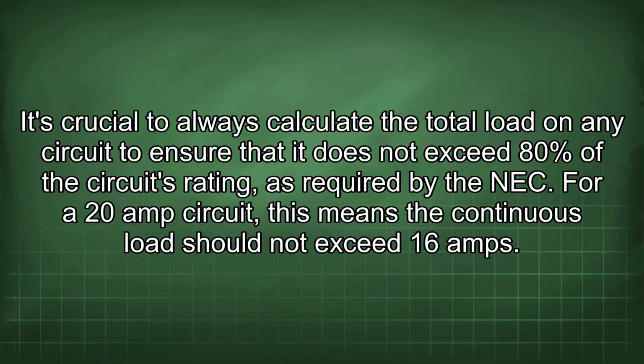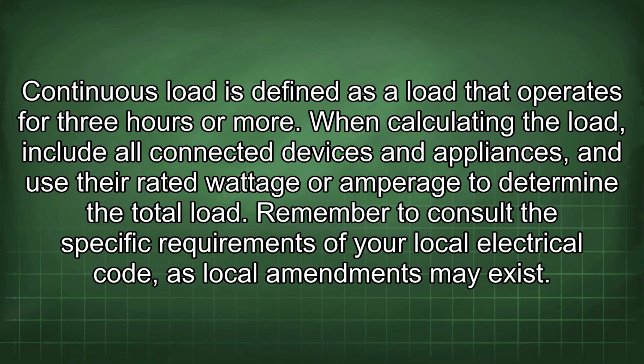It's crucial to always calculate the total load on any circuit to ensure that it does not exceed 80% of the circuit's rating as required by the NEC. For a 20 amp circuit, this means the continuous load should not exceed 16 amps. Continuous load is defined as a load that operates for 3 hours or more. When calculating the load, include all connected devices and appliances and use their rated wattage or amperage to determine the total load. Remember to consult the specific requirements of your local electrical code, as local amendments may exist.